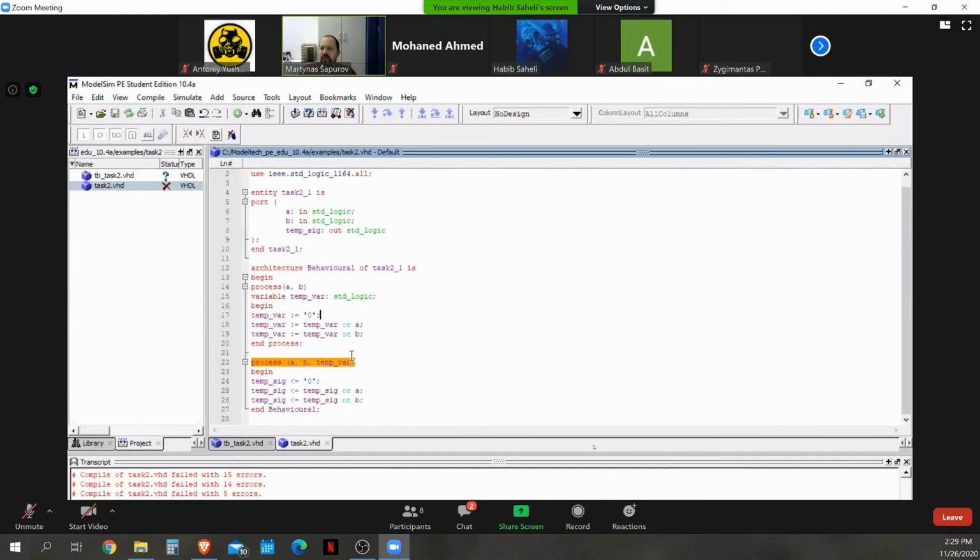That's a bad idea to do it like this. As I wrote you, a signal must be before the begin of the architecture, and not here, not here. Okay, before this begin, yes. Here. And here it's temp sig.